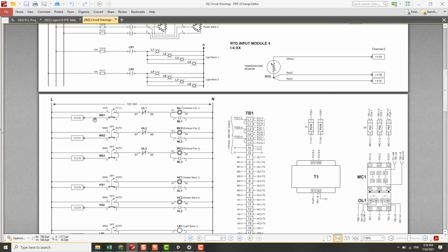Okay, if the upstream is open circuit or having loose termination, the voltage that we measure is 0. Note that this kind of measurement always measures the condition of the upstream, not the downstream. Even if the load is having open circuit, or the circuit after point 3 is having any loose termination or open circuit, it will not be able to detect it. This kind of measurement always detects the upstream. Actually, this is a very basic concept. Everybody should know. Okay, so now we measure here.